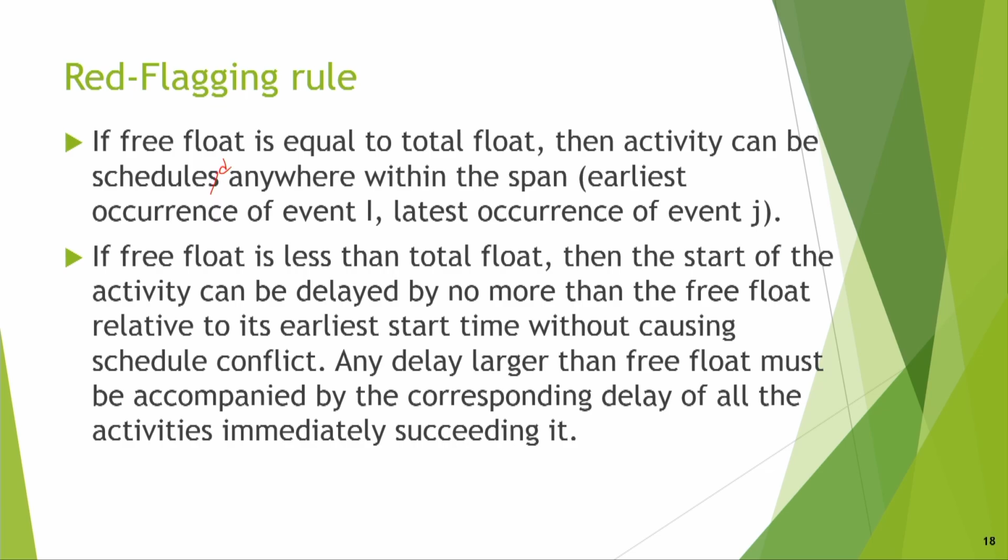Although you have freedom, if you delay beyond that, other activities will also be delayed. Any delay larger than free float must be accompanied by the corresponding delay of all the activities immediately succeeding it.